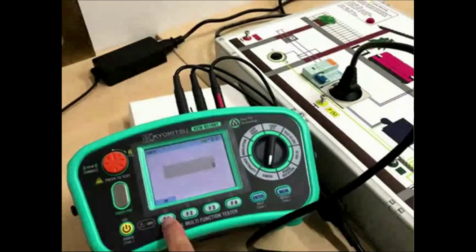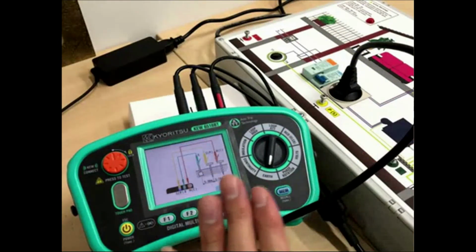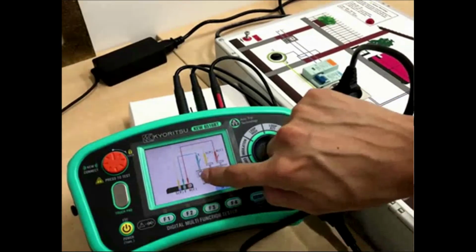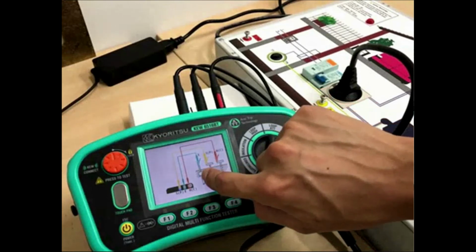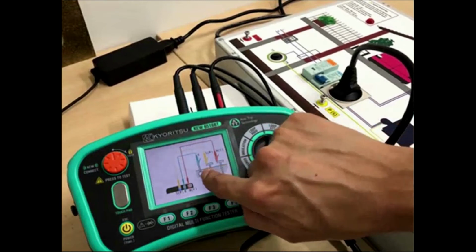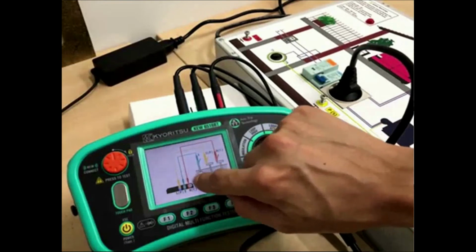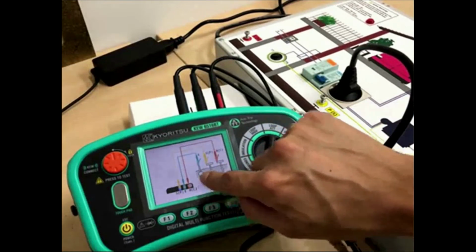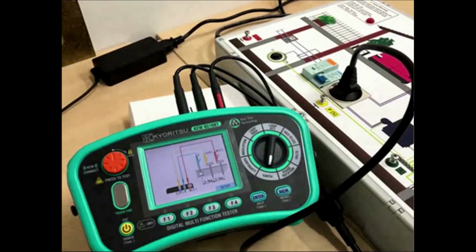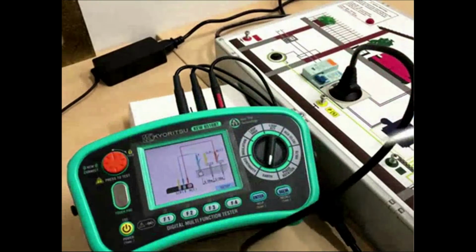Okay, 3-wire. You see, you press enter, top key. So this is the 3-wire method. There is an electrode. This is the electrode under test here. Just now I showed you the equal potential. The electrode is very important. It's the main ground of your building. This main ground must be designed properly because it is your main earth. So this is the auxiliary spike. When you test the earth, you need this auxiliary spike.